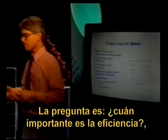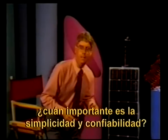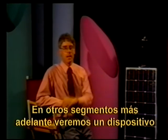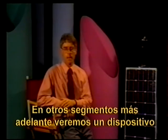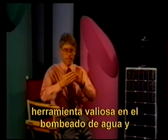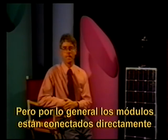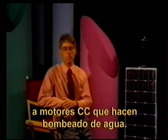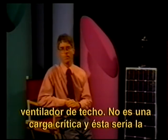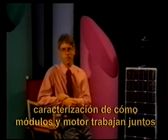The question is, how important is efficiency? How important is simplicity and reliability? They're both important, so you've got to somehow make a trade-off. Later on in other segments, we'll look at a device called a maximum power tracker. In the case of water pumping, it becomes quite a valuable tool and can make this match up better. But it's often common to have modules directly connected to DC motors doing water pumping. Another example might be modules connected to a ceiling fan to give ventilation. It's not a critical load, and this would be the characterization of how the modules and the motors work together.